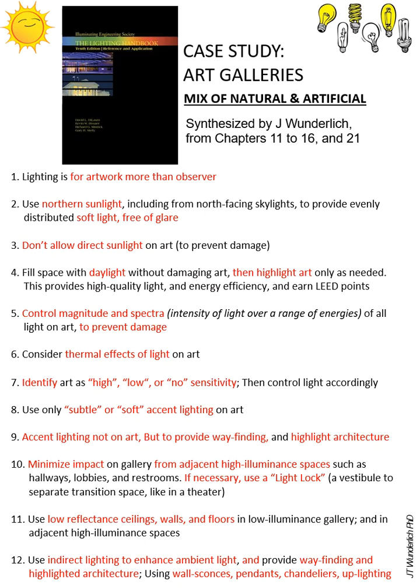You want to use northern sunlight for soft light, free of glare. Goes for all studios typically. Don't allow direct sunlight on the art. It can damage things. Daylight first, and then highlight art as needed, only if needed. Control magnitude of the spectrum, the intensity, distribution of the energies to prevent damage. So you want to really consider that. Your art conservators can tell you more about that when you're designing the space. Thermal effects of the light, right? You don't want to heat it up. Identify high, low, or no sensitivity art, so you light accordingly, or exhibit accordingly.